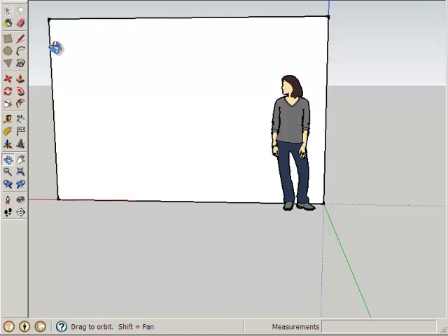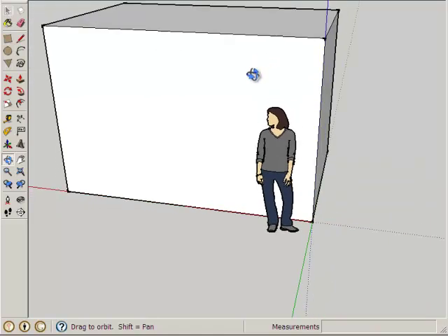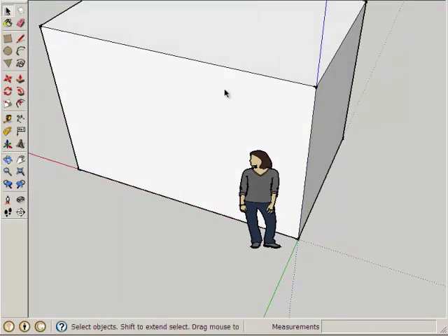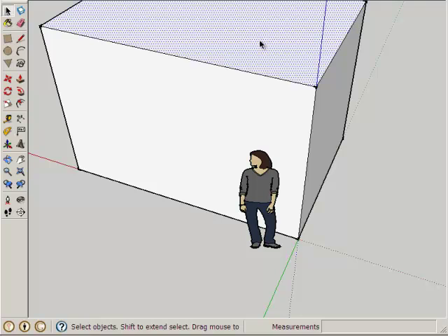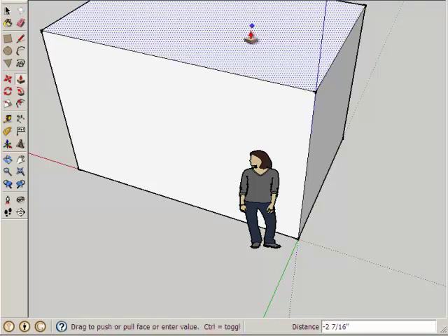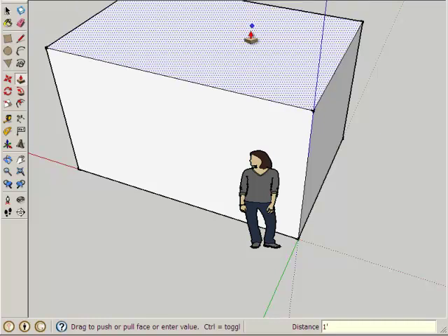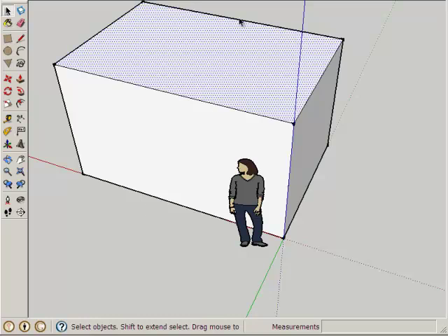So I'm going to have a roof pitch starting in the center and maybe going down 1 foot. I'll do this by shrinking this box here. I'll select this top surface, use my push-pull, and I'm going to go down by 1 foot. Type in 1 foot, hit enter, and then I'll make my line to go across the center.